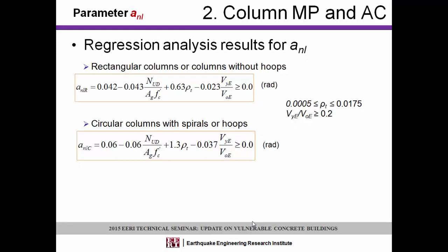So these are equations, no longer tabular format. You have the axial load, the transverse reinforcement ratio, and that Vy over V naught term. More axial load has a negative sign, reducing that parameter.